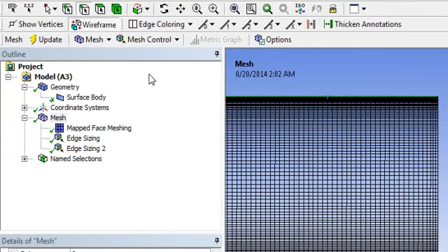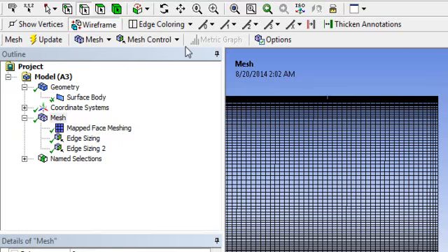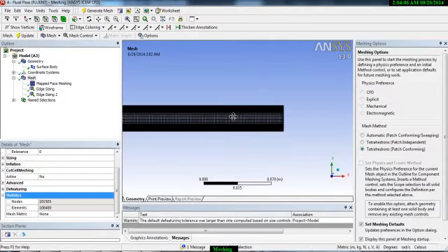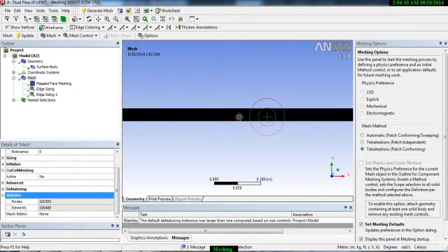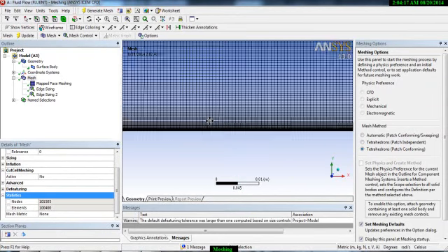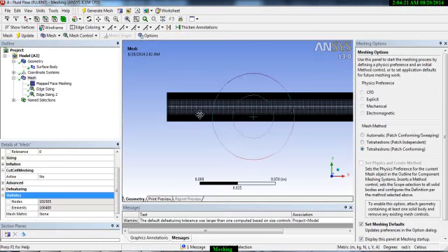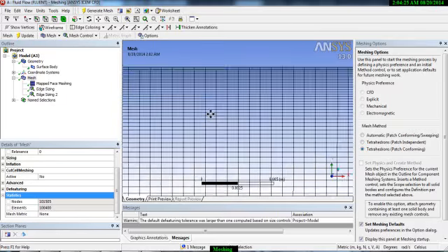You can also play with different tools to change the mesh size, but if you really want to resolve the boundary layers, you need a very dense mesh close to the wall. That's why I chose 2D simulation first, because in 2D you can use many nodes to resolve the boundary layers first.